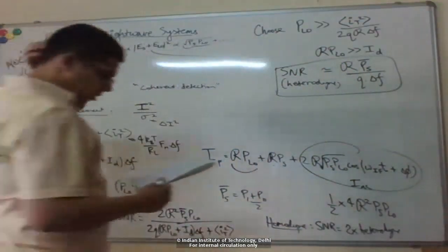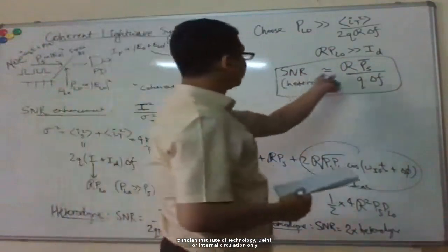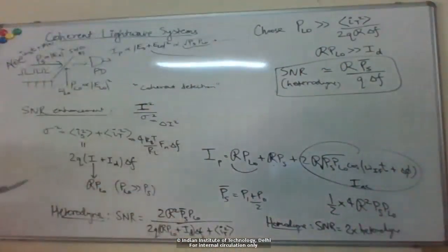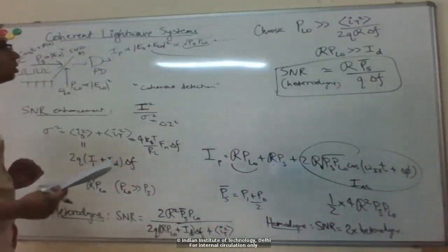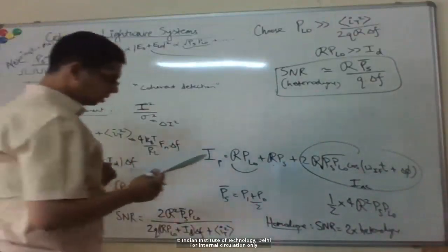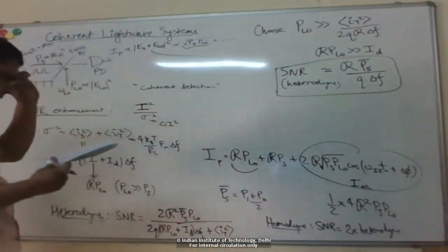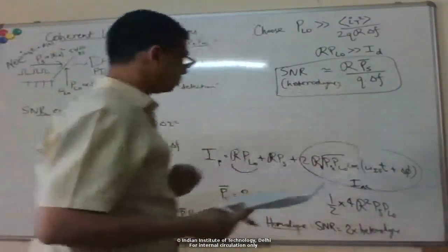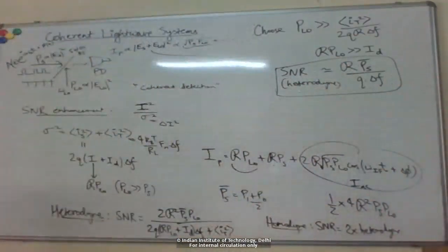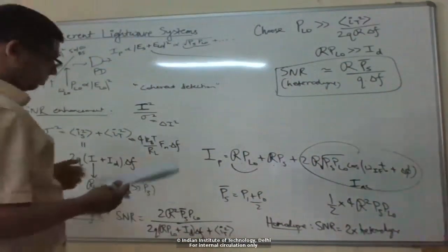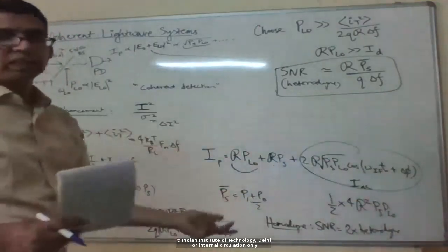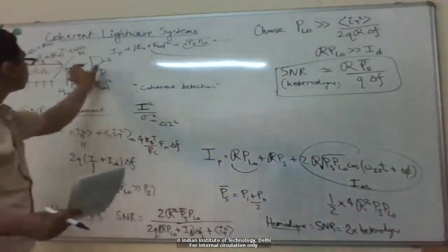Okay. So the SNR just scales with the signal power linearly. So this is basically like the shot noise limit. Okay, and the point here is that we can get into the shot noise limit even by using a pin